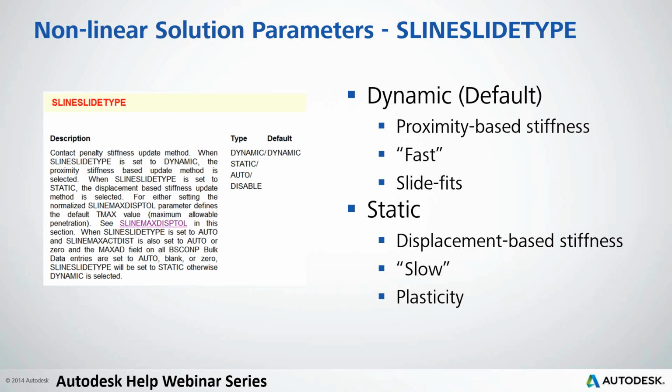I'm going to talk next about static, which should not be used with slide fits. This is a displacement-based stiffness, and it's meant for slow contact. So you're moving 1 to 2 elements over the course of an increment.